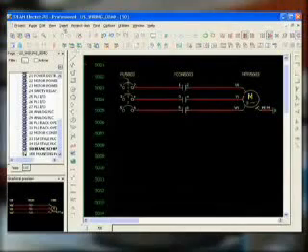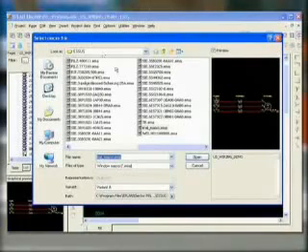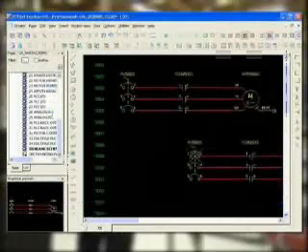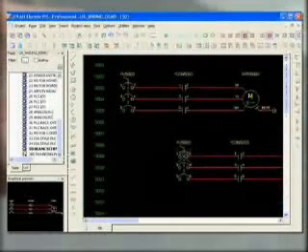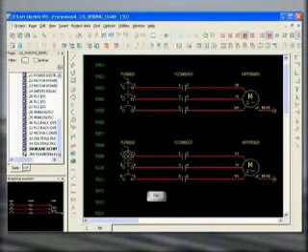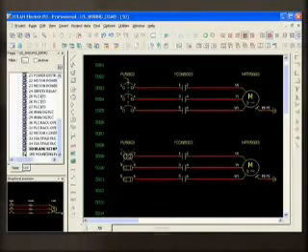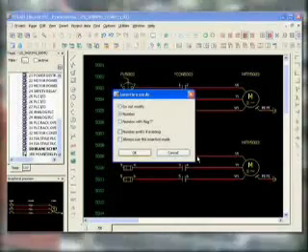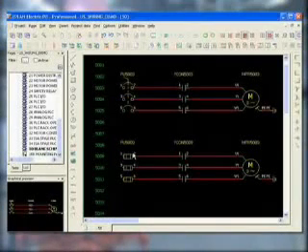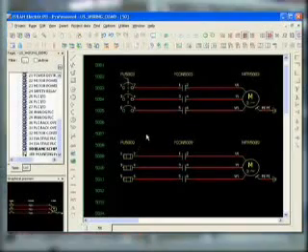To insert the macro into the schematic, select Insert and Window Macro. Select the macro you'd like to place. Move the macro to the correct location. Variants can be accessed via the Tab key. Eplan can also number all of the devices automatically. All of the symbol properties and part information are saved in the macro as well. This macro can be used in any project.